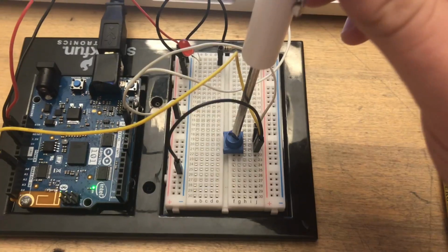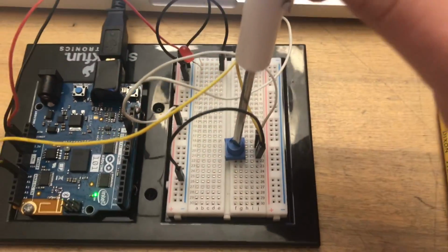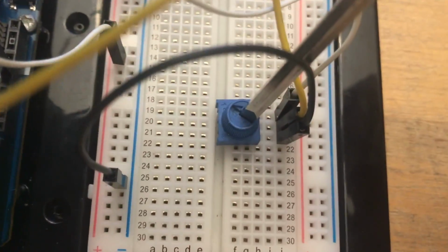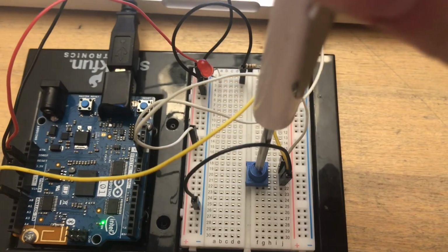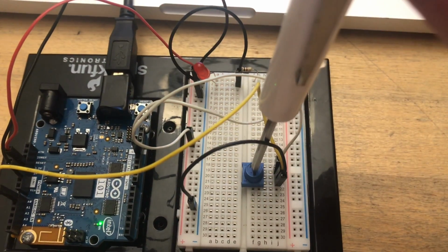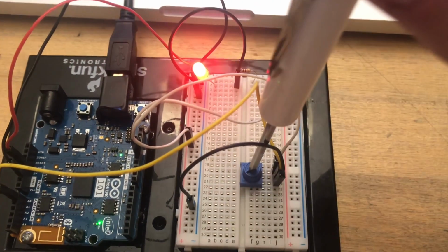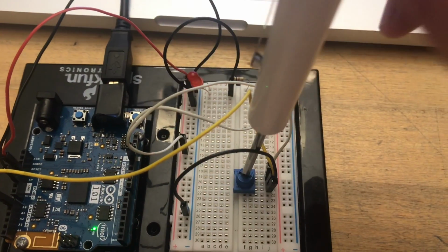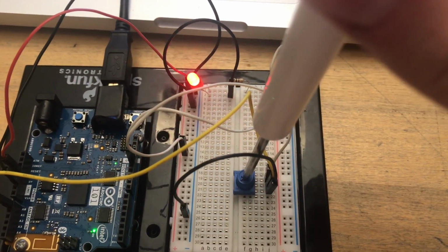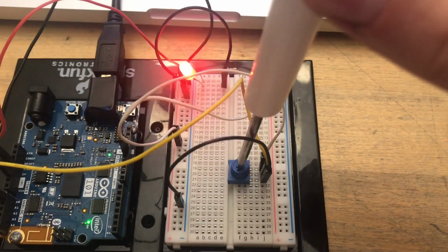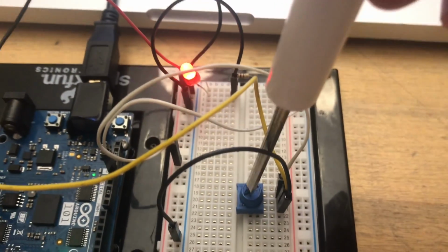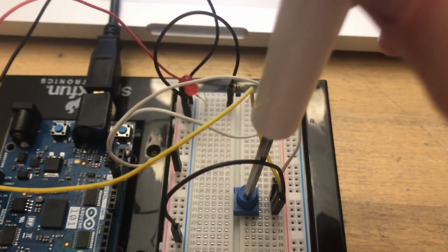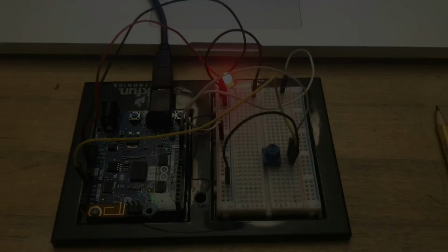Now we see the LED blinking, and by using our screwdriver, we can change the rate of the blink by adjusting the potentiometer. So right now it's all the way over to the 1 on the potentiometer right here, making it the slowest blinking. And as we move it all the way to 3, then the blinking gets faster. And then when we get all the way over here, it blinks very fast. There we can barely see it blinking, but if we go back over, then you can see it blinking. And there we go, all done.